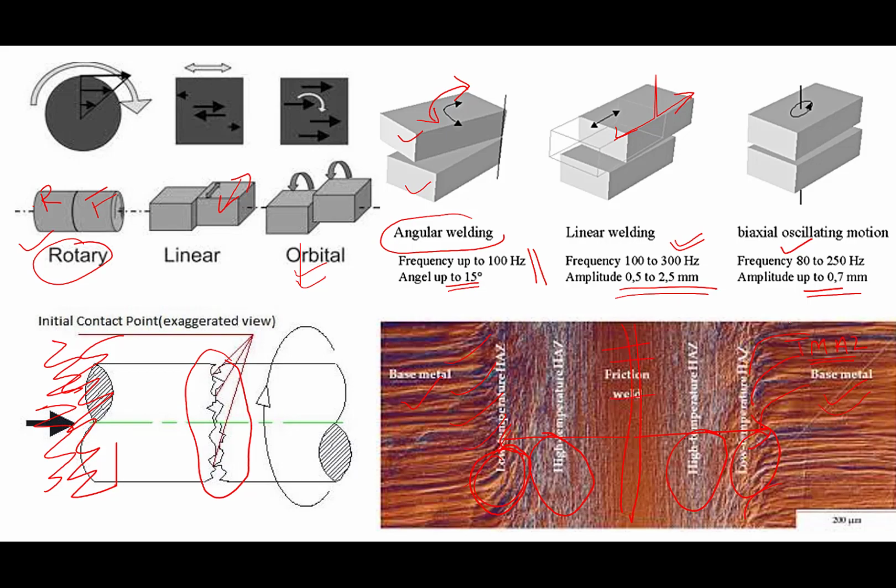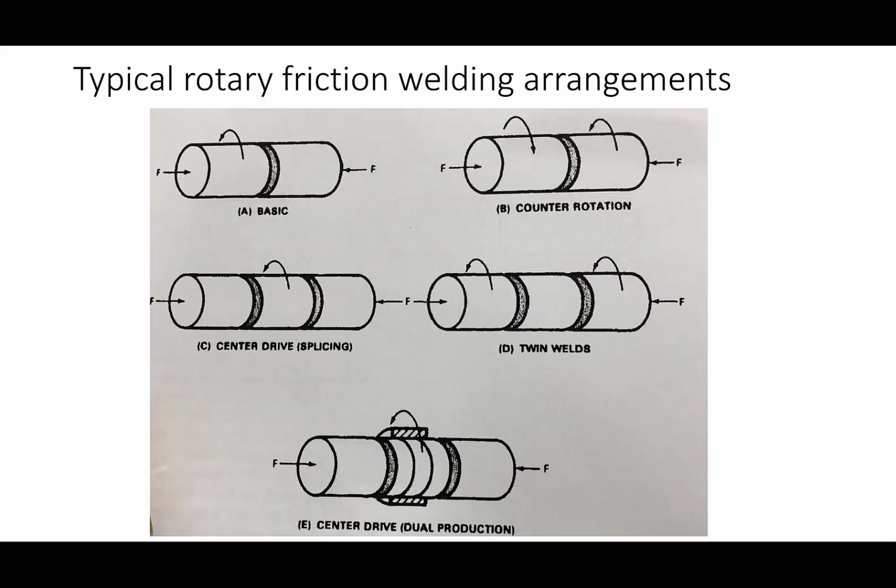Now depending upon the size, if you notice, this scale is 200 micrometers. So the weld zone size may be 100 micrometers or so, where you have significant refinement, structural transformation, or the metallurgical changes that will be encountered. Thereafter, from the joint interface up to around 200 micrometers on both sides, there is a heat affected zone. That's how you can see it.